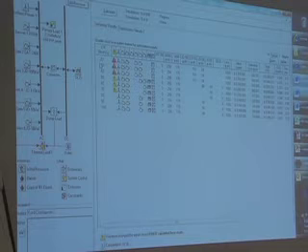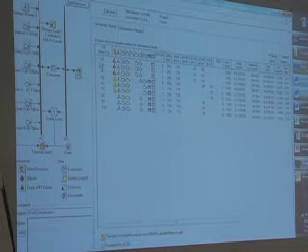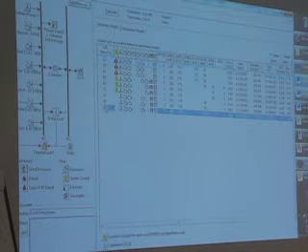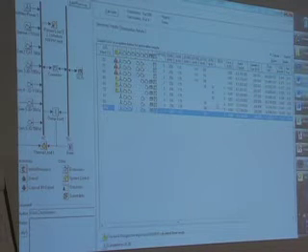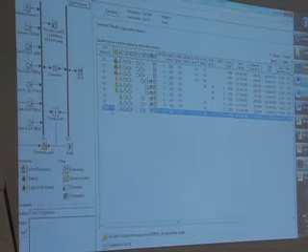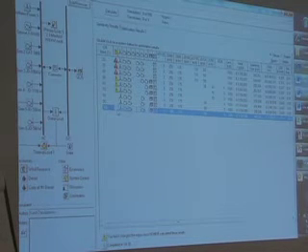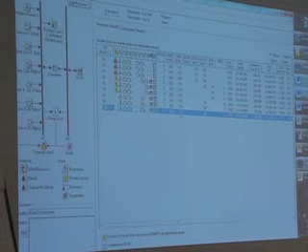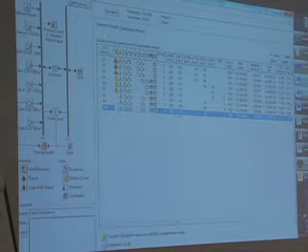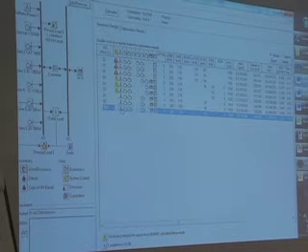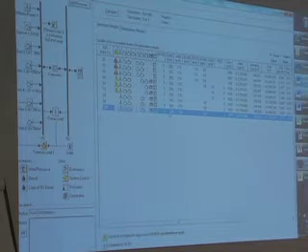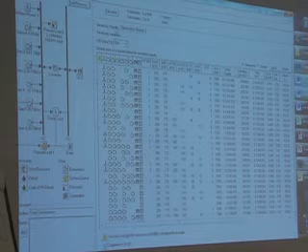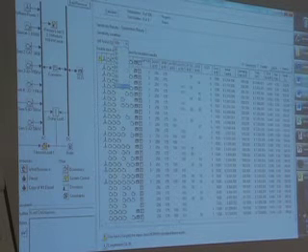So I expanded the space a little bit, and I said, let's look at operating reserve requirements all the way from 20%, which is pretty aggressive, all the way up to 100%. And it makes a big difference. Even at 100% operating reserve, 3 wind turbines are still cost effective. To look at that case in more detail, we can double click on there, or we can just go up here between sensitivity results and operating results and find the case that we want to look at.